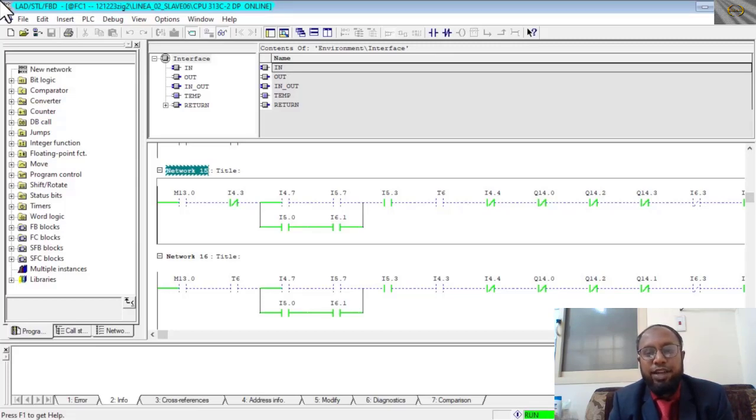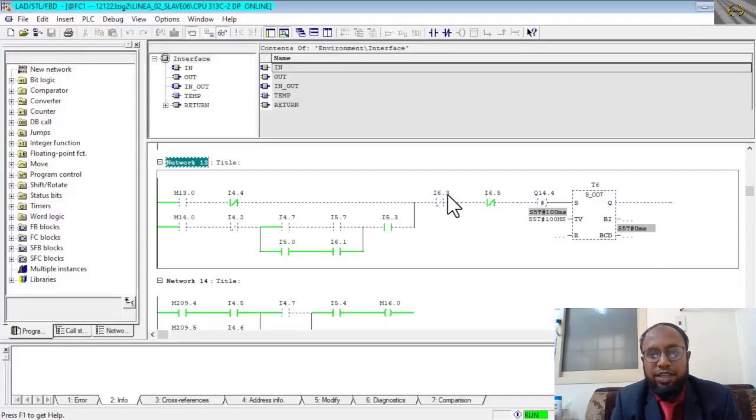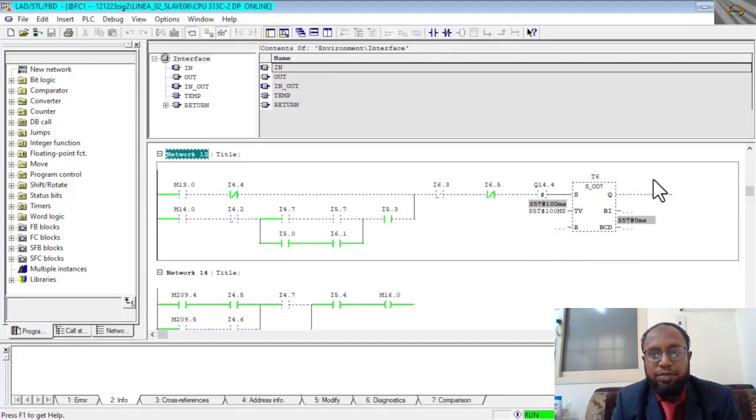Now we are checking another thing, how to run T6. First, we have to see in our backup program comments what the condition for T6 is. Now we are seeing here. This is T6. T6 depends on some of the sensors or limits, I4.7, I4.2 like this. Now we have to understand in which area locations those limits are giving the signal.